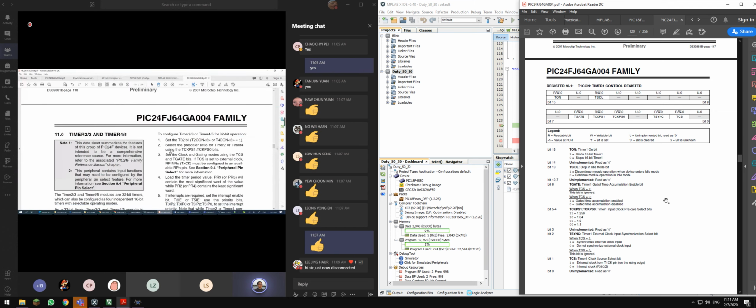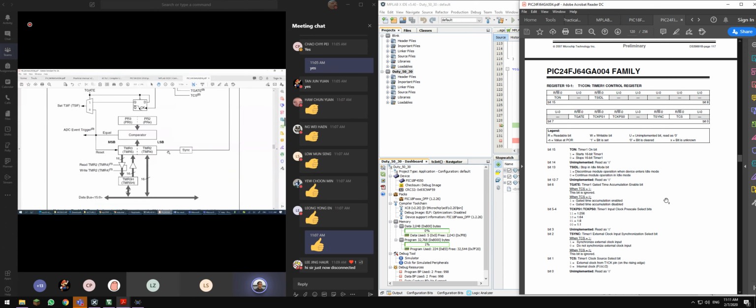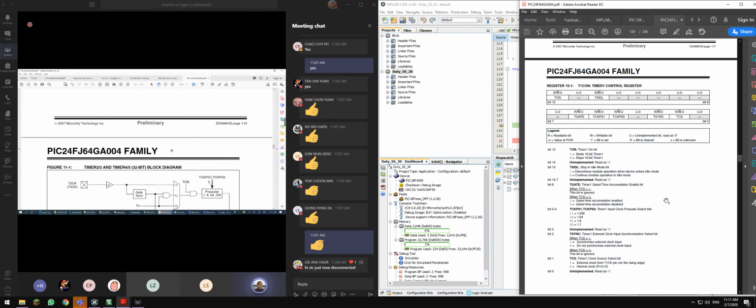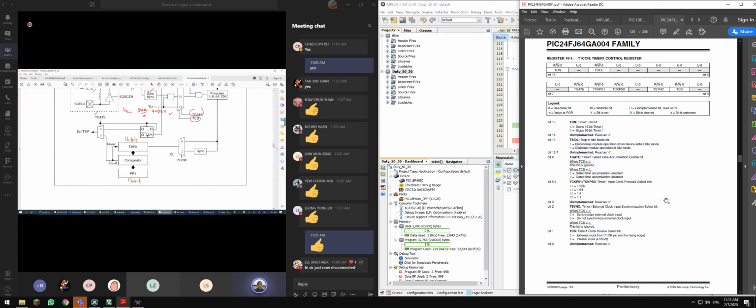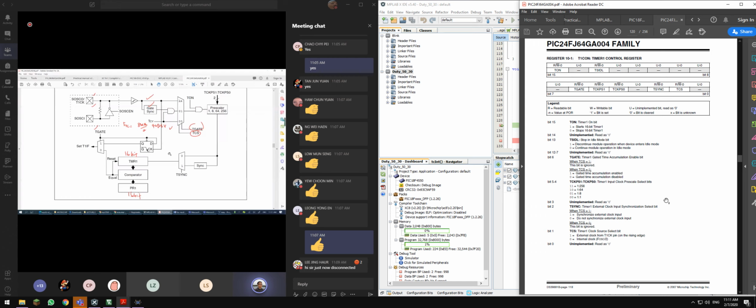So what is so unique about this? Actually, this style is exactly the same as Timer 2 in PIC 18. But PIC 18 is 8-bit, this is 16-bit. Now it's very simple. Whatever value you put inside here, when I start the timer, TON switches it on.